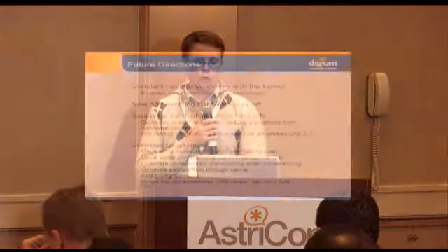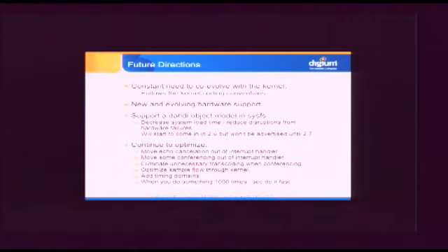And then there's always the move to optimize. So moving the echo canceller out of the interrupt handler is in the works. Moving conferencing out of the interrupt handler. A lot of the mixing happens in an interrupt handler right now in DAHDI. Eliminate unnecessary transcoding when conferencing. A lot of times when you're doing conferencing, things get transcoded to ulaw and signed linear back and forth several times. So that can be optimized.